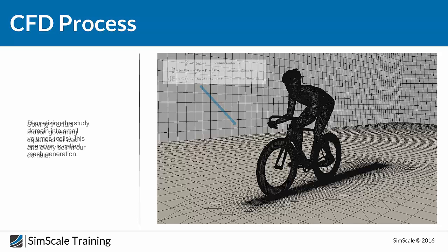The next step will be to apply these equations, this mathematical equation that describes the movement of the flow of the fluid over space. And here we have what we call the Navier-Stokes equations, which is the continuity equation, the momentum equation, and also the energy equation. But for this case, we are not using the energy equation because we don't have any compression condition and thermal effect.